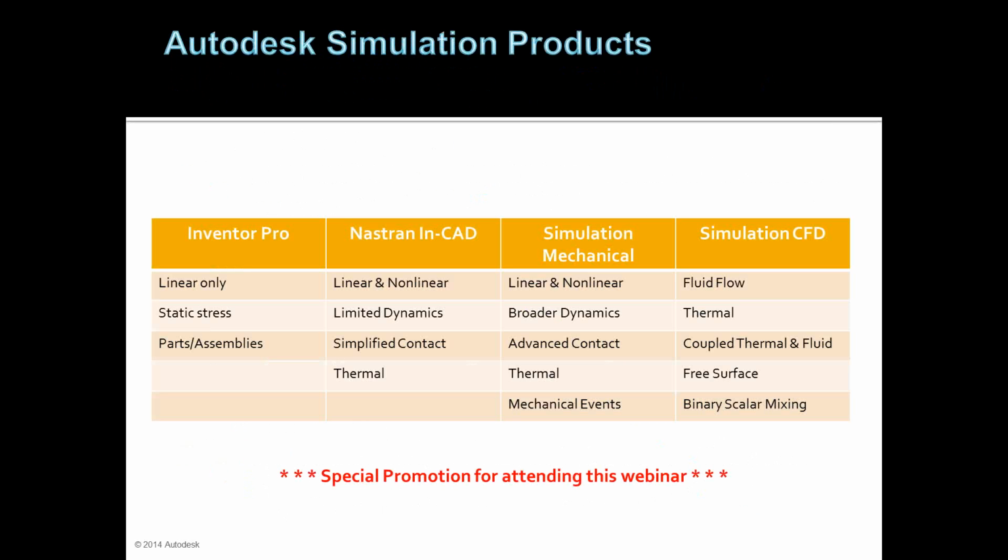It will do thermal and also mechanical event systems, movement inside of your assembly. If those will not fit the bill, we also have Simulation CFD, which focuses more around fluid and thermal flow through a system or through an environment. You can do coupled thermal and fluid, so heated water versus cold water, which also gets into your mixing at the bottom. You can see how those two fluids will mix and change the temperature dynamic through that system, as well as free surface simulation.